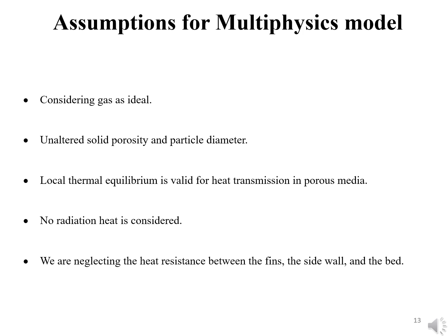So the next slide is about all the assumptions we took for our multiphysics model. The first one is that throughout the hydration process, the gas is handled as an ideal gas. The second one is the solid porosity and the particle diameter of porous medium, which is thought of as a continuous medium, stay unaltered during the hydration process. Since the temperature of solid phase and the gas phase are equal during the hydration process, the local thermal equilibrium is valid for thermal transmission in porous media.